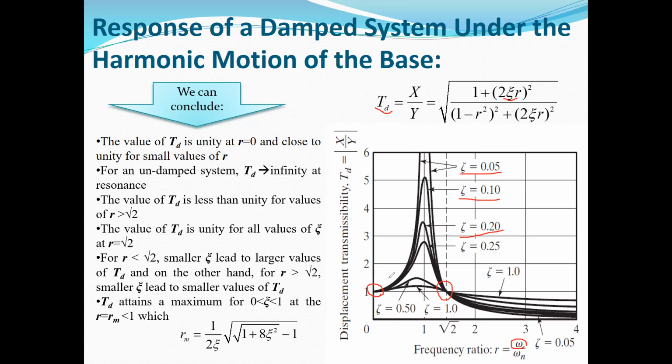And usually in a car, we prefer to decrease the amplitude of the response, because when you decrease the amplitude of the response, or decrease the uppercase X, in fact you are decreasing the motion of your car, and we usually prefer to decrease and vanish the motion of the car relative to the motion of the base or the bumps.